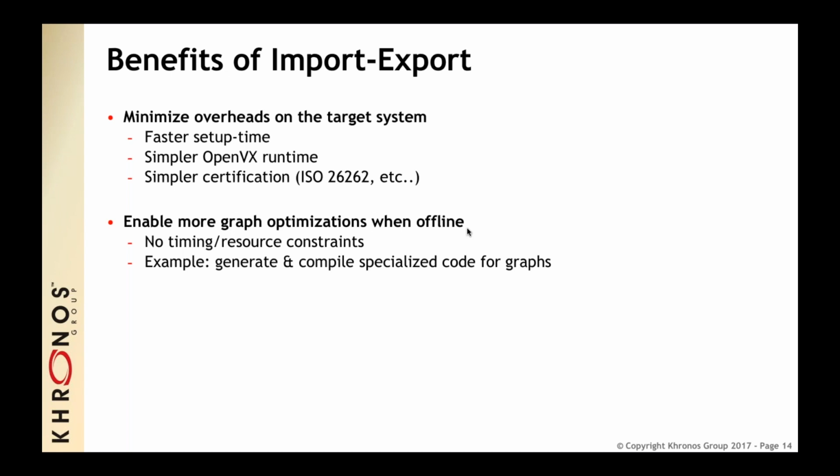This reduces the number of features that a safety critical application developer has to worry about, and that reduces a lot of overhead. And we try to make sure we pass all the MISRA warnings. We cleaned up everything just to make things easy for the safety critical users here.